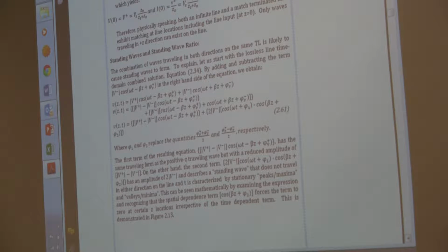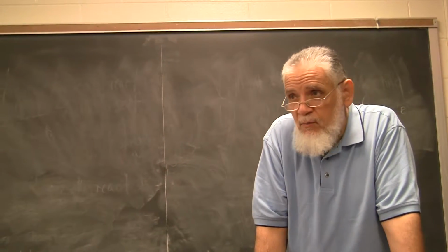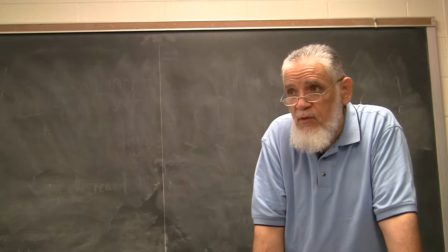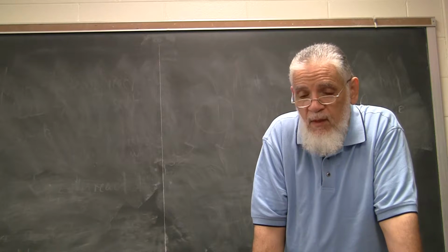So obviously to be able to meet the two constraints simultaneously, you would like to work with pure resistive circuits. If you have pure resistive impedances, like the characteristic impedance is pure resistive, the source impedance is pure resistive, the load impedance is pure resistive, then you can achieve both conditions at the same time.